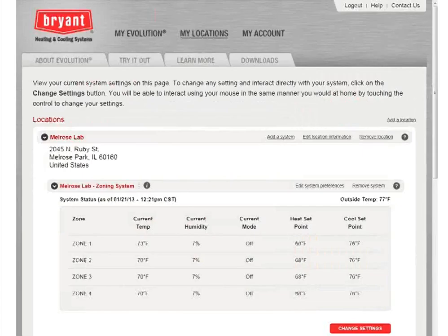There's the video stuff. When I actually log into the stat, I can see all of my zones at one time to see what they're doing. Just like with the Benstar and Honeywell ones, I can have multiple locations, multiple properties, and each property can have multiple stats and systems inside it. So it's pretty similar in that regard. I can change my schedules. I can override my stat temperature, put it in the hold mode, put my vacation mode on, those normal kind of things. I can set it up to send me emails and text message alerts and that kind of thing.